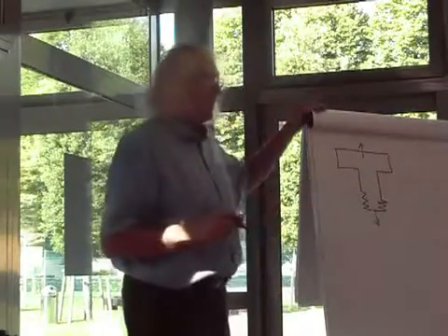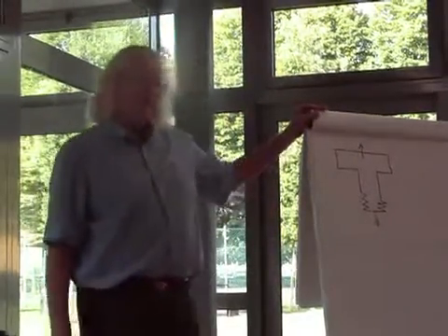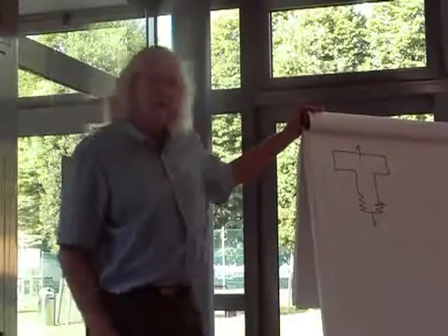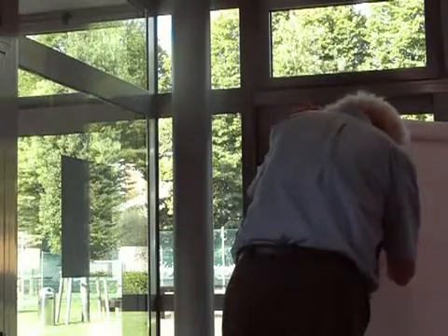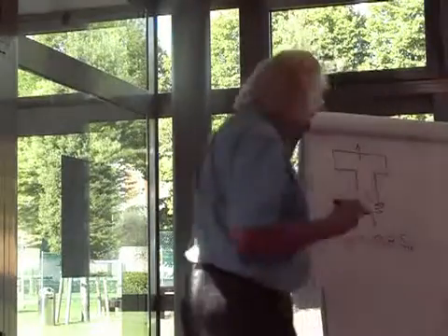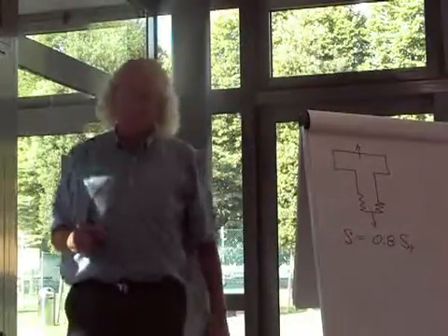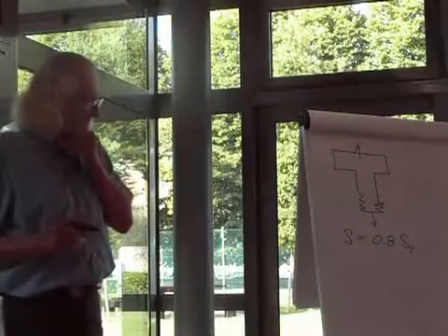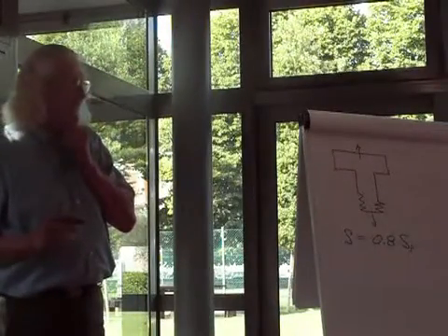And the preload force here is about 80% of the strength. So the stress, statically, is 0.8 times the strength of the bolt. Fine. But that's the nominal stress.